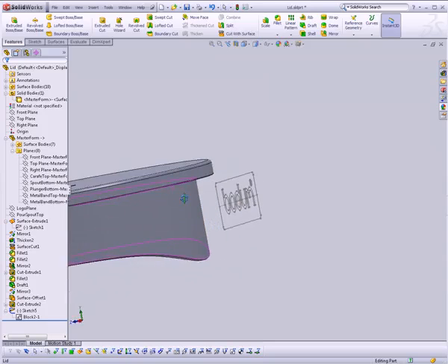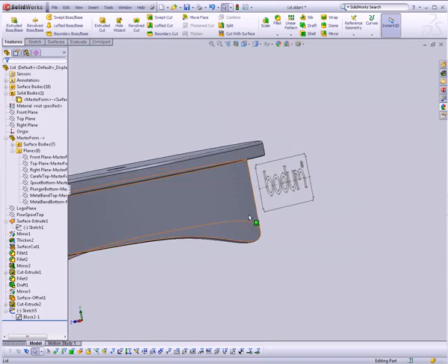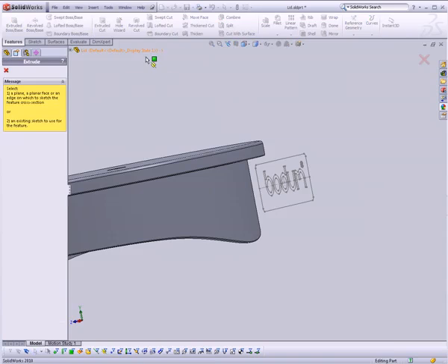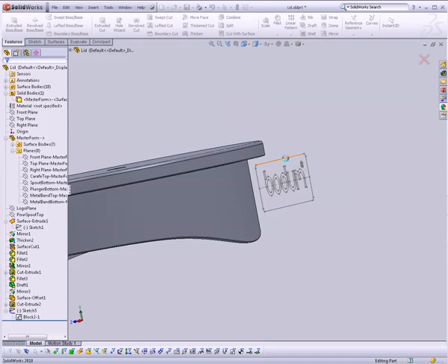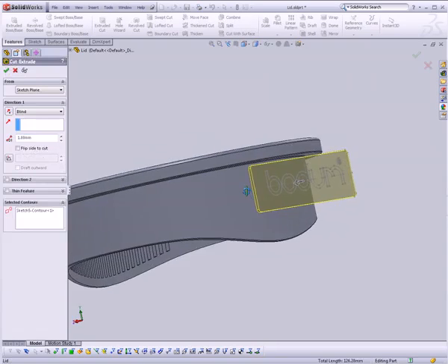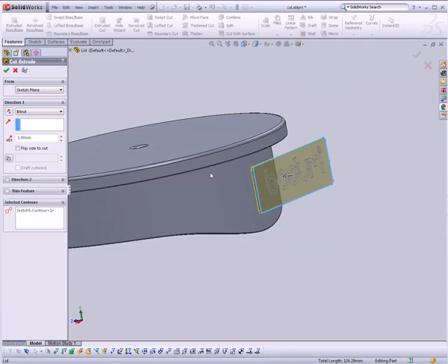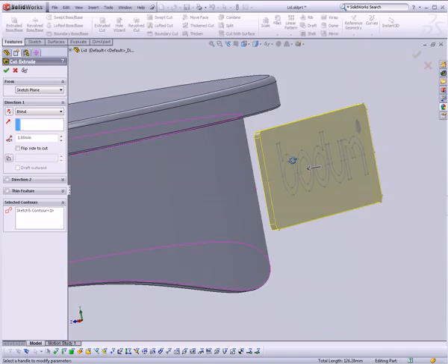Now we just have to get this onto our object. And I'm hoping that's going to be a relatively simple process. Let's keep our fingers crossed, hope for the best. I'm going to do an extruded cut and select this sketch as what we're going to be using as our cut. And by default, because this is a really complex sketch, it's going to use selected contours, and it's only going to extrude this outer piece because that's what I clicked on.